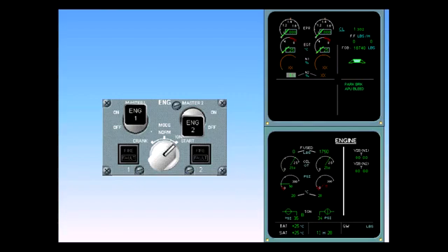In order to provide a more uniform cooling for an already hot engine, the full authority digital engine control will motor the engine for 30 seconds. At that point, an igniter is powered. The active igniter is indicated by its letter, A or B, on the ECAM engine page. The high-pressure fuel valve also opens. This is indicated on the upper ECAM by the indication of fuel flow.